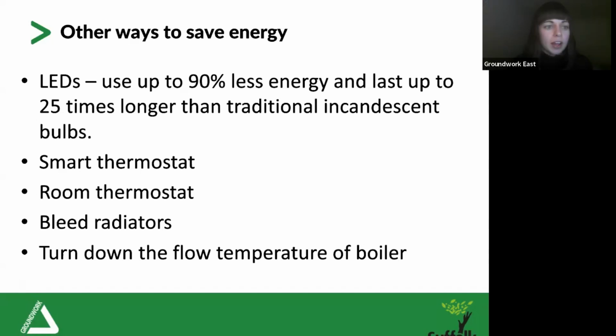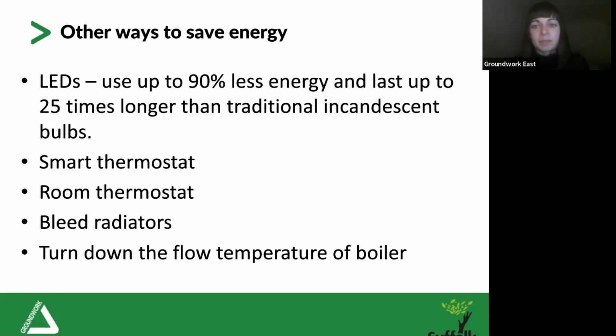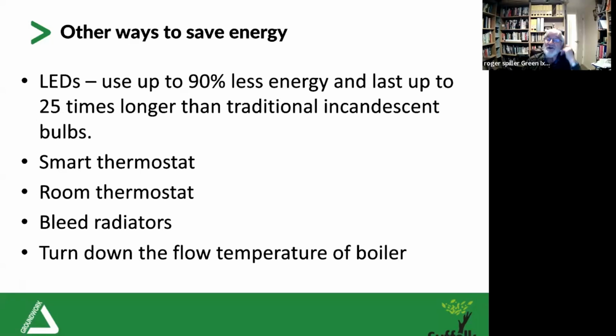Right, that's a good point. Our gaps are quite extreme in our house. I think we need to look at some material that allows that flow of air, but also allows for that expansion. Well, tongued and grooved boards, that's why they're tongued and grooved, because it does allow them to expand and contract while still keeping a reasonable seal.